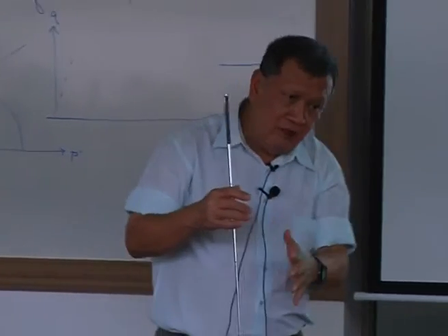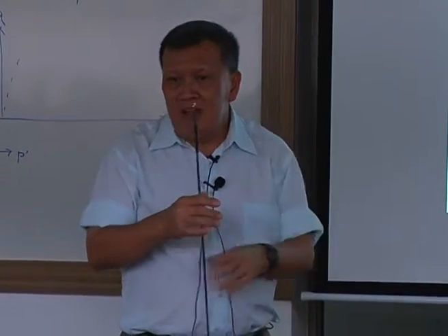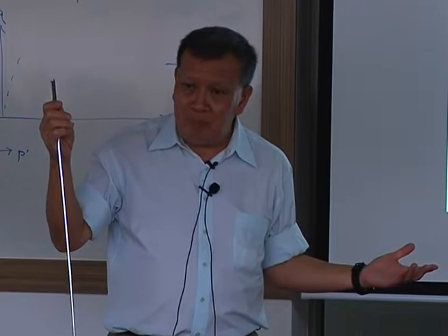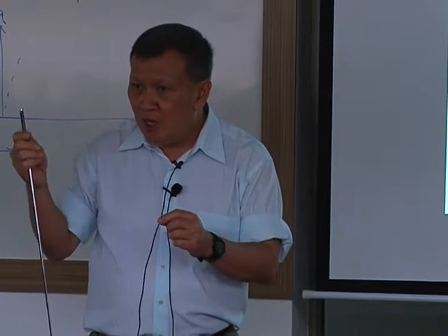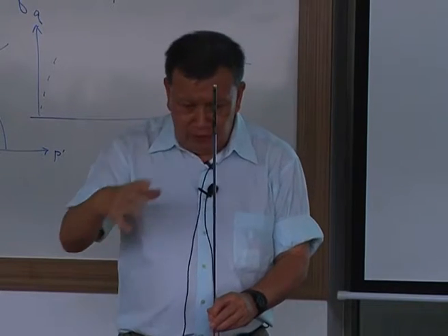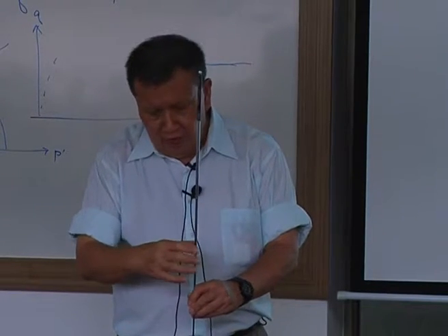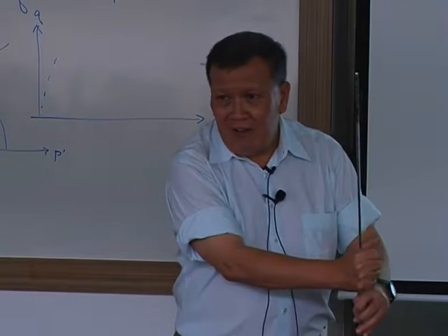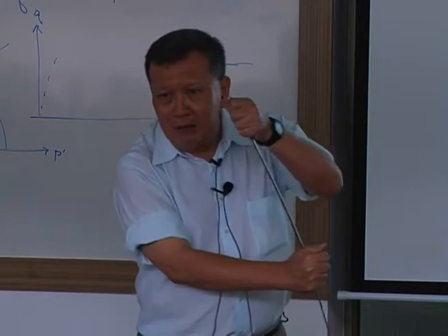So the sand just literally moves through the pile. Okay, the wall will show a larger deflection, but the pile feels less load. On the other hand, if you set a 5 degree angle of dilation, then when the sand tries to shear across the pile, it locks up around the pile and tries to bring the pile along. And so as a result, the pile is bent.